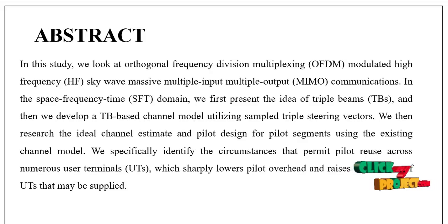This is our abstract. In this study, we will look at orthogonal frequency division multiplexing modulated high frequency skywave massive multiple input and multiple output communication. In this space frequency time domain, we first present the idea of the triple beams, and then we develop a triple beam based channel model utilizing sampled triple steering vectors.